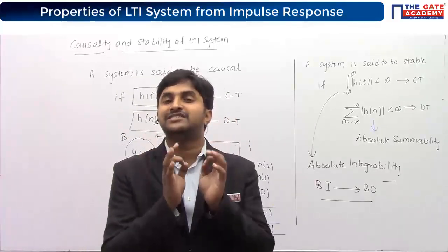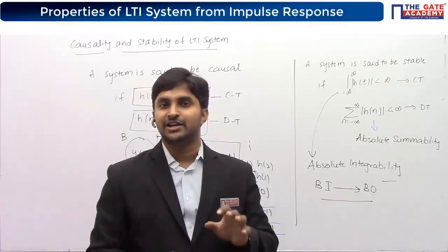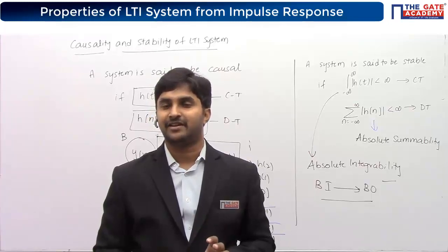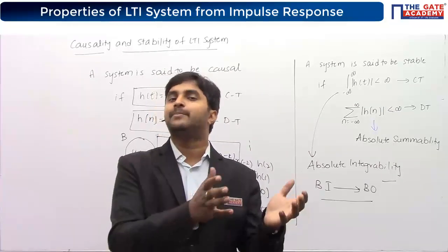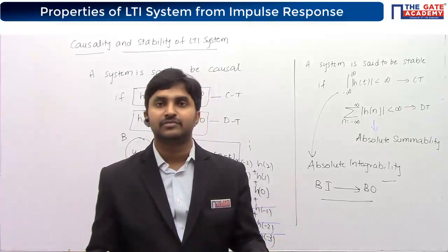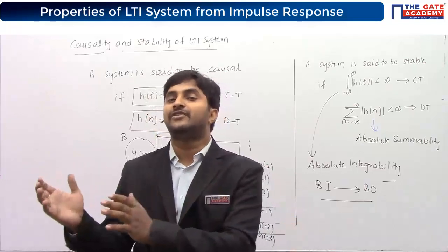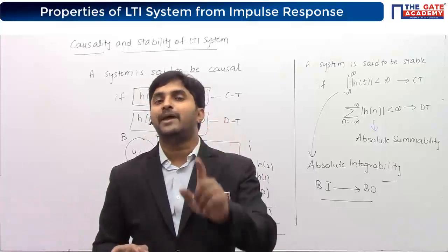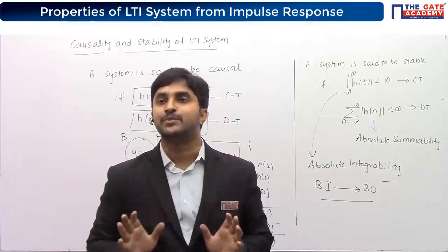If you want to test the stability of the system, you have to ensure that you are applying an input which is bounded in nature. That is the only criteria. So if you are not applying the bounded input, then you cannot expect the system to be stable. Applying the bounded input, you will see whether the output is bounded or not. Even in one case, if you apply a bounded input and the output is unbounded, the system is said to be unstable.